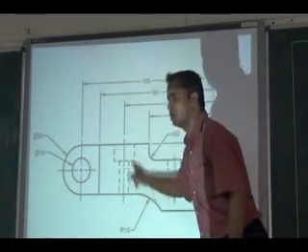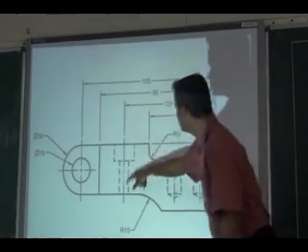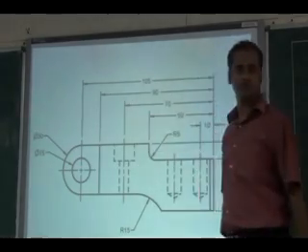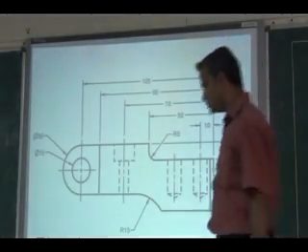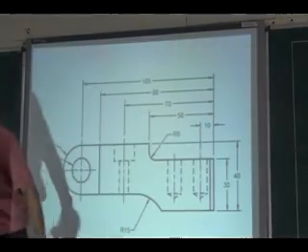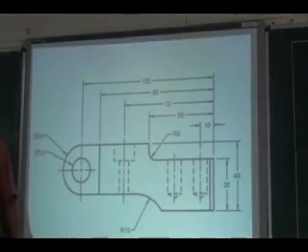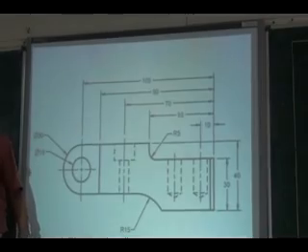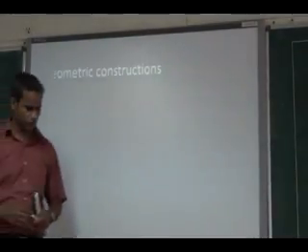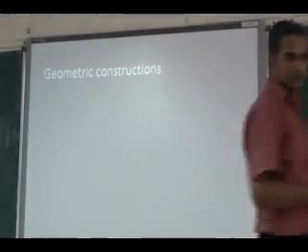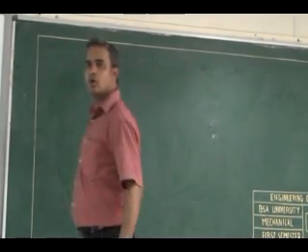So this is a hidden hole. That hidden hole center line, I should not dimension it. I should not show it. Right. So this is the mistake. These mistakes you should avoid in your dimensioning. Is it clear now? So we will move on to the next one, geometric constructions. Again I repeat, show your arrowheads neatly, practice it.